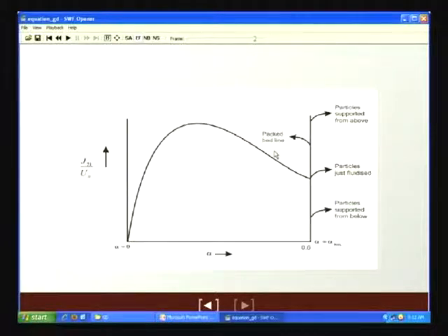So, this is one particular point which I wanted you to remember: for gas-solid cases, since they are very flexible, the curve can extend from alpha equal to 0 to alpha equal to 1. But for fluid particle cases, they cannot extend beyond the critical value of alpha, which gives you the maximum limit of solid packing. Beyond that, solid-solid interactions become important, and the basic assumptions based on which I had made the derivation are no longer valid. Okay. So, beyond that we cannot proceed.